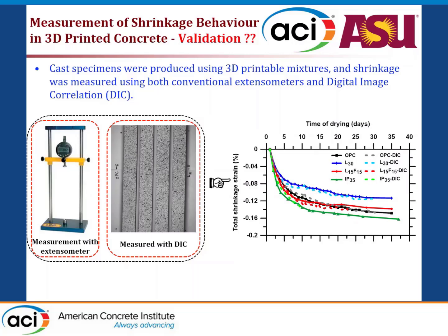So the bold lines here are the measurements from the actual extensometer, and the dotted points are based on the DIC measurement for each day. Again, for the DIC measurement we took a frame each minute. We can do it over longer periods, in terms of hours and so on, also, but we did it at 1 minute, and we have a lot of data which we are filtering out and showing fewer points, but we do have a bunch of points. But if I plot it all here, it will just look like a messed up point collection.